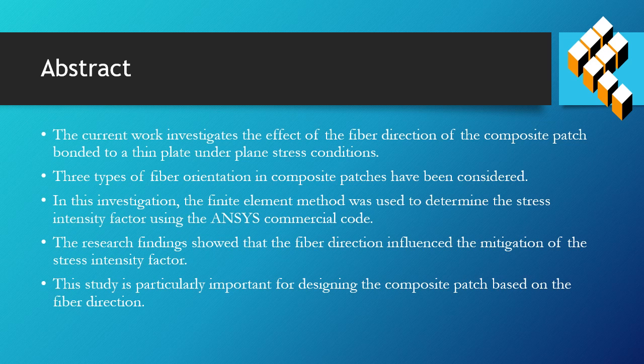In my paper, the abstract is that the main aim of the work is to investigate the fiber direction of a composite patch bonded to a thin plate under plane stress condition. Three types of fiber orientation in a composite patch have been considered for the current work. In the investigation, the finite element method was used to determine the stress intensity factor using the ANSYS commercial code. The research findings showed that the fiber direction influenced the mitigation of stress intensity factor. This study is particularly important for designing a composite patch based on the fiber direction.